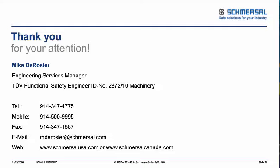Okay, next question. How often do we need to test safety devices such as light curtains or laser beams? With something like that, if it's a specific device, you need to look at manufacturers' recommendations to test that the device is functioning properly.